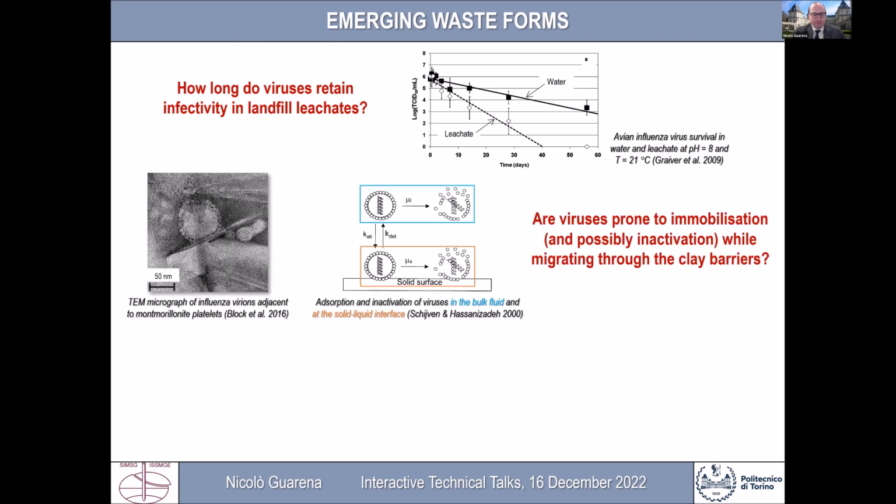When the pathogen transport through the bottom lining systems has to be addressed, the ability of viruses to undergo attachment and detachment processes on the solid particles within engineered clay barriers raises the issue of their survival time in the adsorbed state. According to the limited experimental evidence available to date, the inactivation rate is expected to decrease following attachment to the clay particles, at least under near-neutral pH conditions.